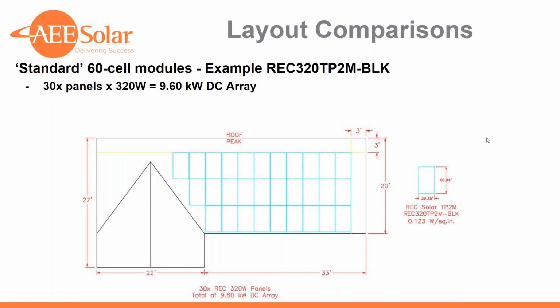With the 2-to-1 aspect ratio, these stack nicely. If you needed to, you could do something really similar in portrait. You could probably mix orientations here if you really wanted to squeeze in maybe another row along the top. You could do the top row and this row in landscape and really maximize the output of this roof. Note here, in some of these comparisons, 3 full rows of portrait, and we're able to make use of most of this roof valley along this hip. So let's move forward.